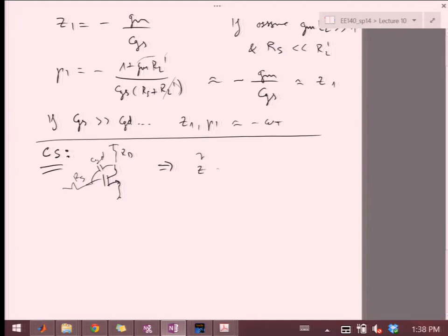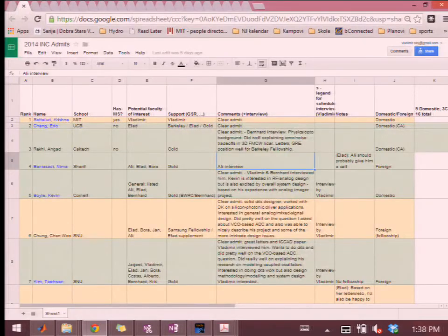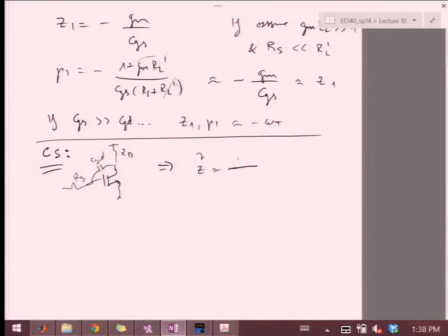it's actually of this form, and it's actually a right half plane zero, so it's not a negative sign there. Although this is very small, it will play a role when we start doing the stability analysis. Now we're just doing the frequency response, but once we get into the stability analysis of multi-stage amplifiers, you'll see that this feed-forward zero would have a bit of a role.